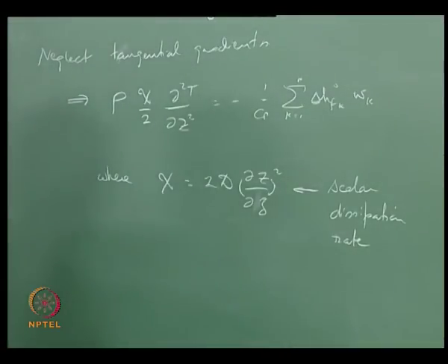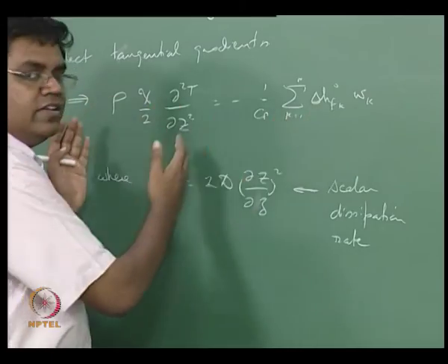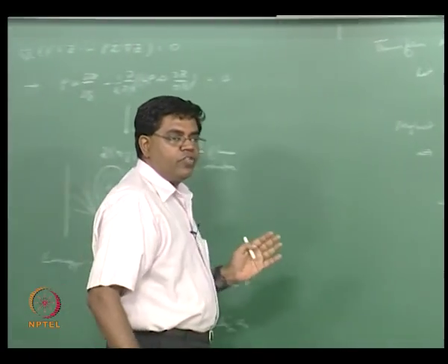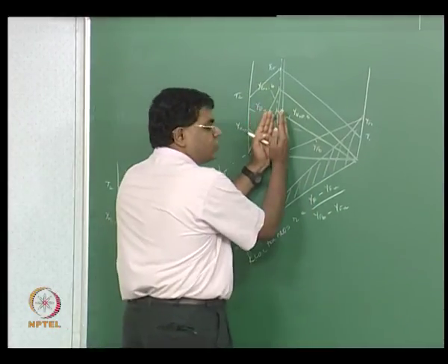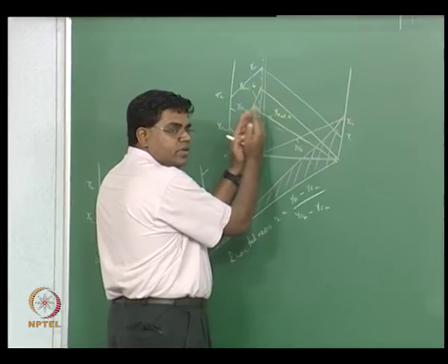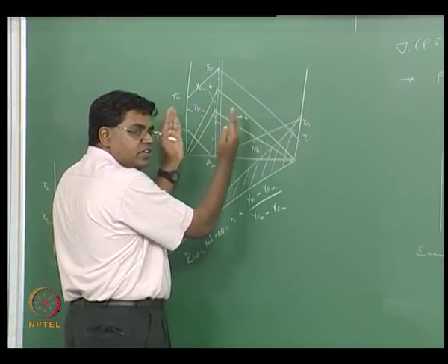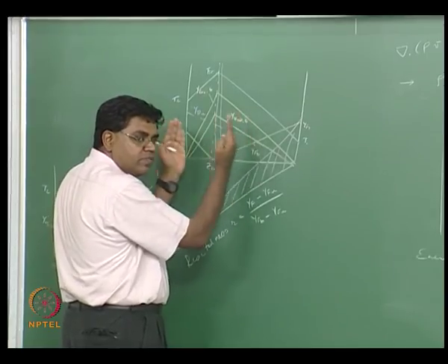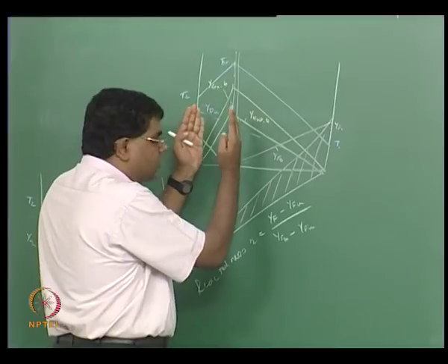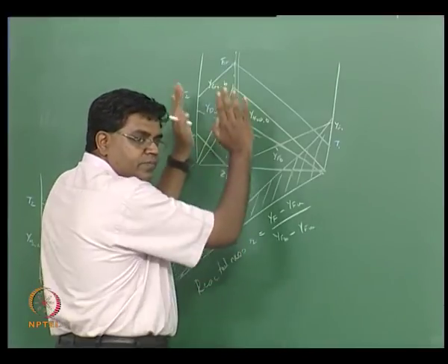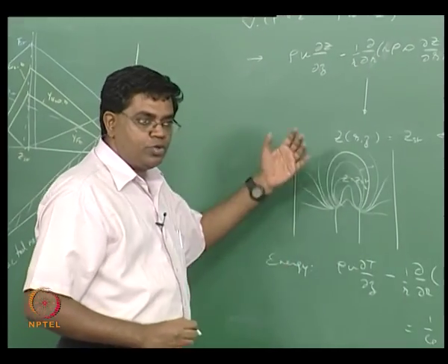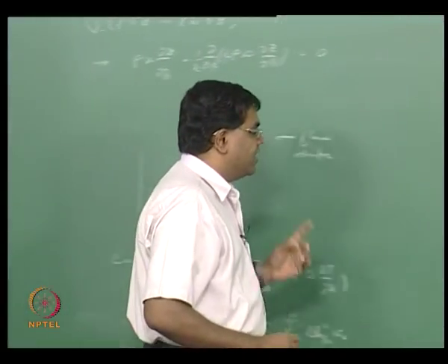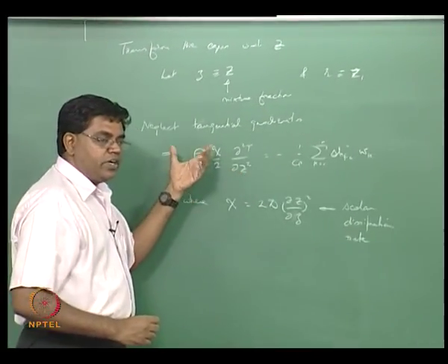Now, it will look like essentially a diffusive reactive balance that we saw for the reaction zone in the premixed flame, and I also pointed out that this region is going to be like the reaction zone in the premixed flame, and whatever is outside of this in the near vicinity is going to be like the preheat zone in terms of transport processes dominating, except it's going to be radial transport versus axial convection and so on in the Burke-Schumann problem, or any co-flow diffusion flame problem like jet diffusion flames and so on, except this is not really a diffusion term alone.